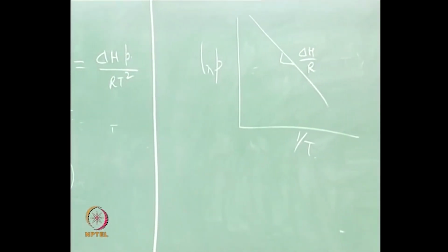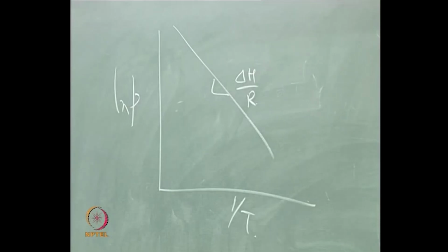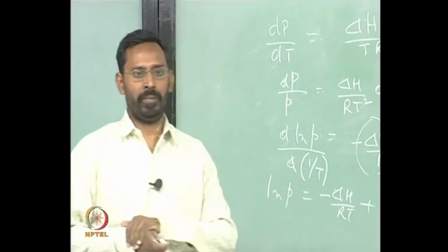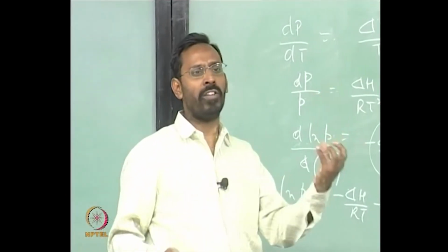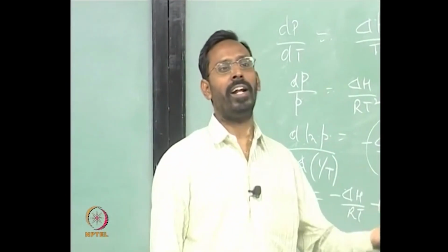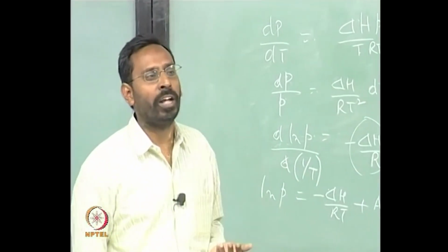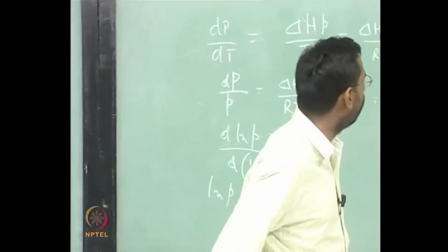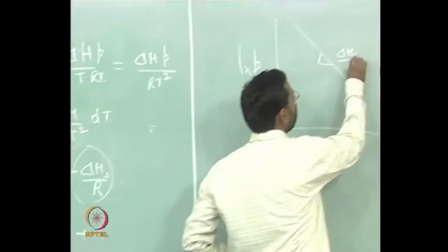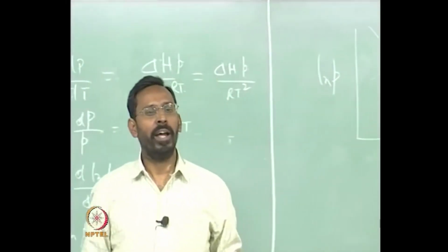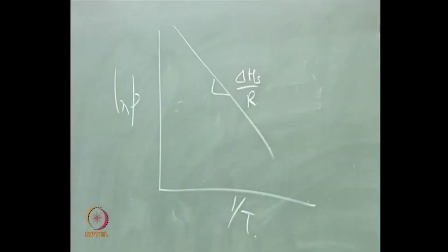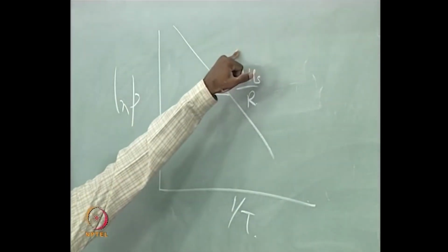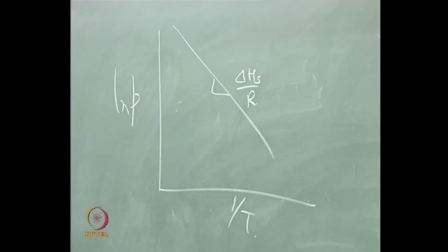This is expected because if the sublimation enthalpy, the delta H associated with sublimation, is very large, then at any given temperature, because you need more energy for the sublimation, the amount of gas molecules generated from a solid is always going to be lower. So particularly when we are looking at metals with a higher boiling point, a metal with a higher boiling point basically means its delta H of sublimation is very large. That is when you will have a very high boiling point. So whenever the sublimation delta H is very, very large, you would say that this material is more difficult to sublimate.